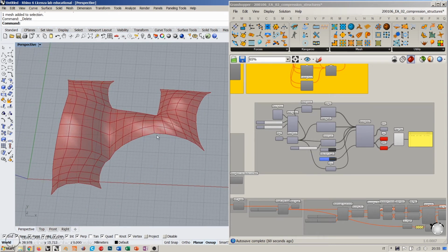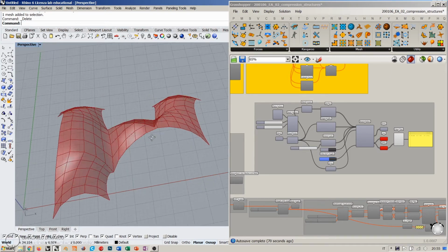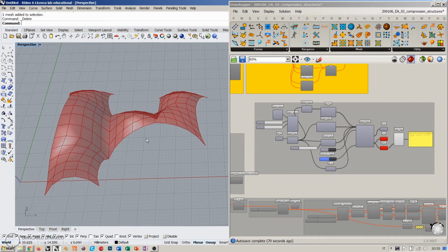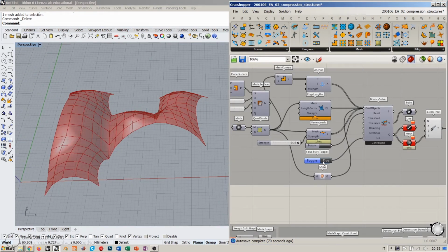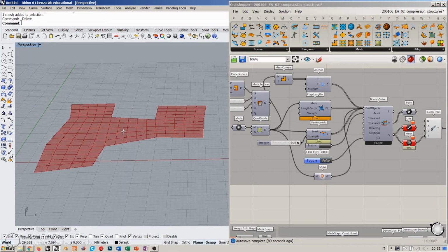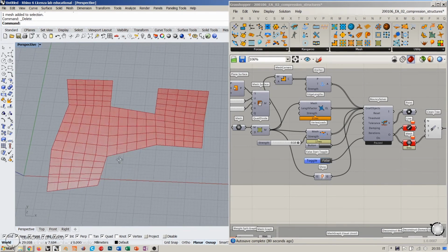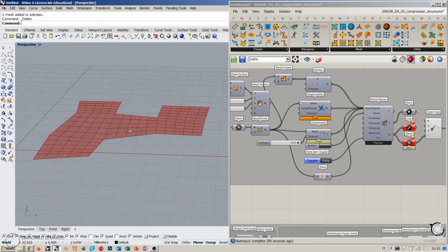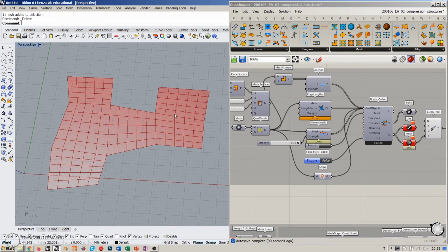Now there are two problems that we must discuss in order to bring this object to real life. First of all, if we consider, for example, the original mesh, the system before the deformation, you see that all these faces here are quad polygons, so they are basically made up of 4 sides, and they are flat. Okay, so if you want to produce these panels here, it's very simple. You can simply cut them using whatever type of cut technology you might want to use.